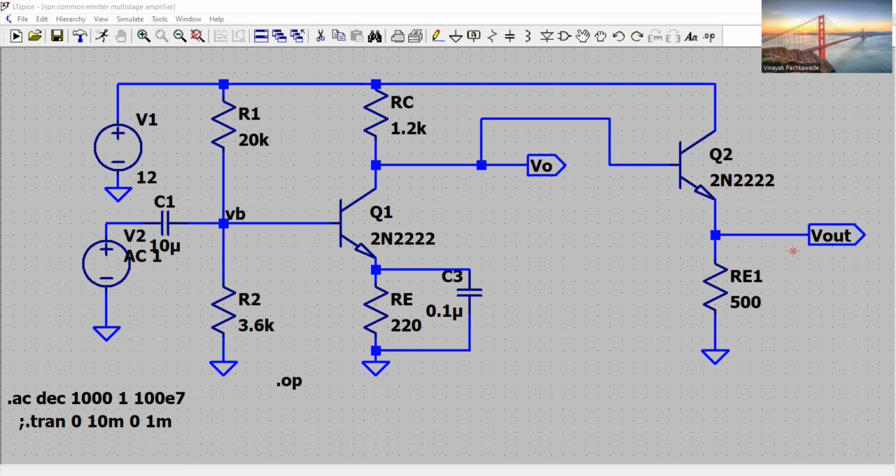We have seen this circuit in our previous module. We got the design of this amplifier in such a way that we use the transistor 2N2222. This is a general purpose small signal amplification transistor, where the gain of the common emitter amplifier is set by the ratio of resistor RC divided by the resistor RE.